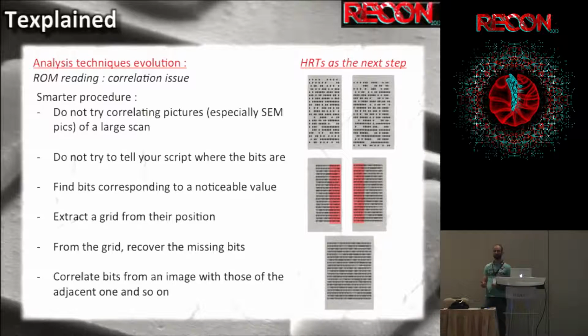How do you design a chip without a grid? It would be insane: how do I place the things? The things have to match on different layers and everything. So they use a grid. The trick will be to detect the grid, as we just did on this ROM. And when we have the grid, we can do a lot of things, finding features and putting them all together.